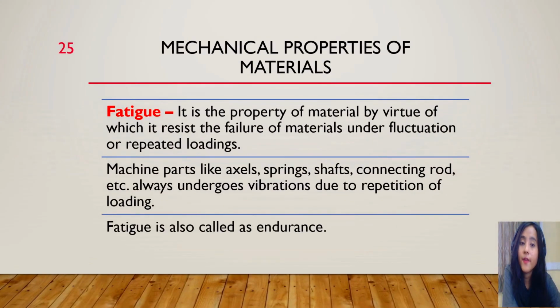Next I have fatigue. Now what is fatigue? Material fatigue is a phenomenon where structures fail when subjected to a cyclic load. Cyclic load means repetitive load. This type of structural damage occurs when the experienced stress range is far below the static material strength. Fatigue is the most common source behind failures of mechanical structures.